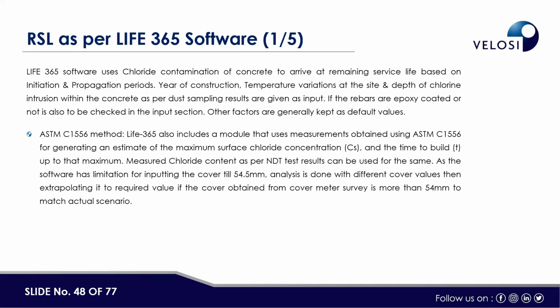Once there are pores or micro cracks there, the agents will start propagating into the concrete. Once it reaches the total depth of the cover, the reinforcement becomes available for attack. So these chemicals will start attacking the reinforcement. Once the passivity of the reinforcement is lost and the chemicals start attacking the surface, it will start forming rust, and it will start bulging out.